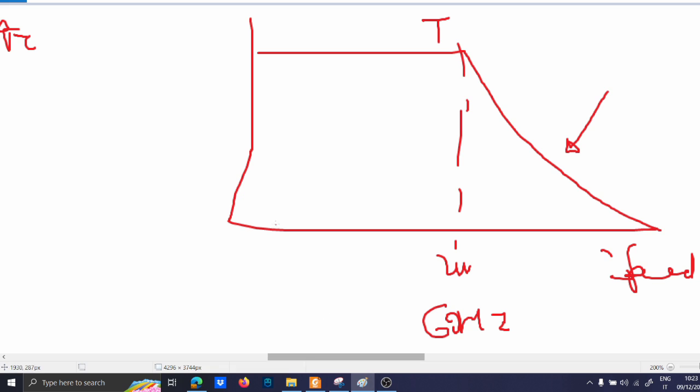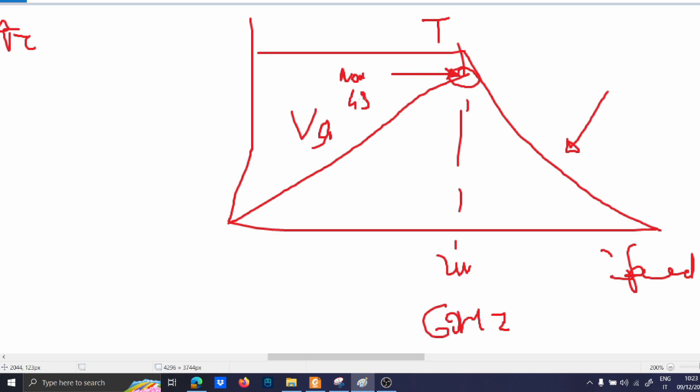characteristic. And to reach this torque here, you have to go to the voltage, and you have to increase the voltage until you arrive at the nominal voltage, like 48 volts, 24 volts, and so on. In this region, you generally keep the voltage constant, and you diminish the torque with the flux weakening. Most of the motors are like this.